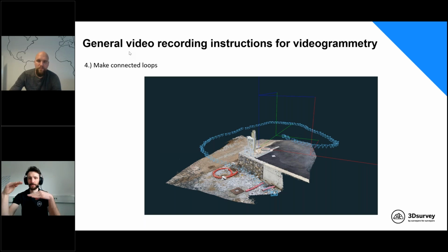This way you will connect the recordings and you will get a double check on heights, and it generally will produce more accurate results. If you don't do that, you may get some discrepancies like a double sidewalk or a curb or something like that, and, well, a less accurate result.